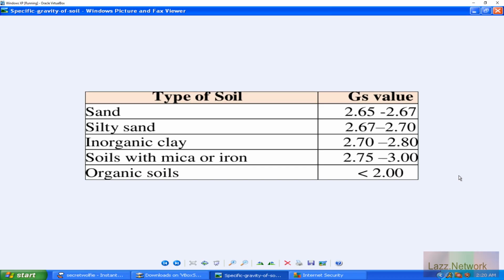Yes, there is grass and things like that that could be in the sample, but usually that kind of material is removed because we're trying to use it for construction purposes. But you still have roots and organics that have stained the sands, that wrap themselves around the sand and give it an organic presence.